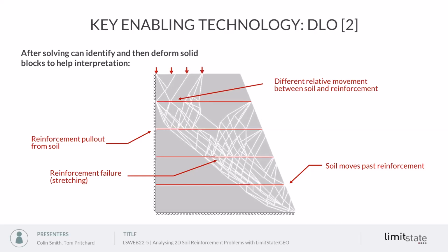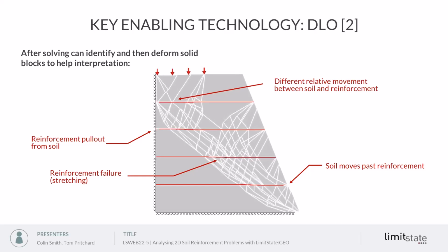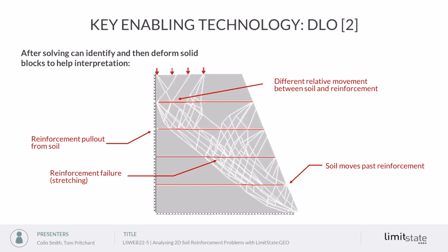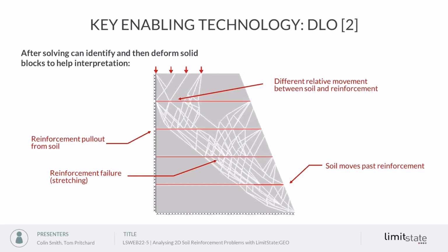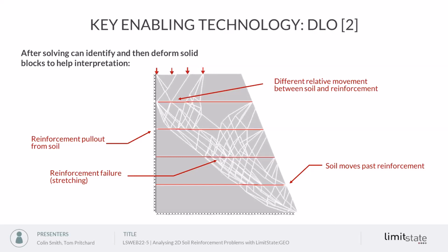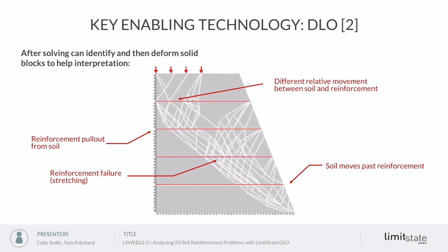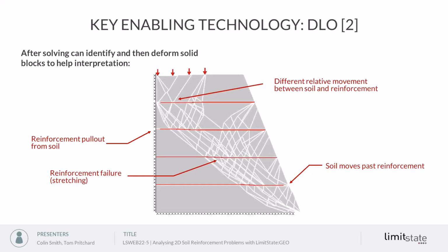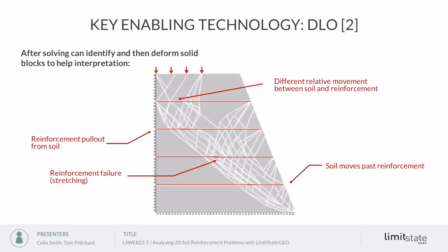So that's an overview of the discontinuity layout optimization software. It basically generates slipline mechanisms formed of effectively thousands or hundreds of sliding wedges, and can integrate that with the conventional approach to modeling soil reinforcement interaction.